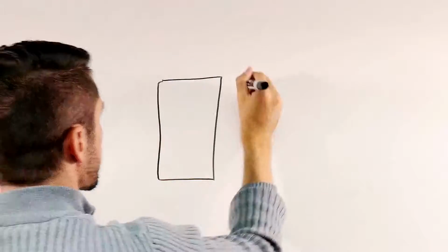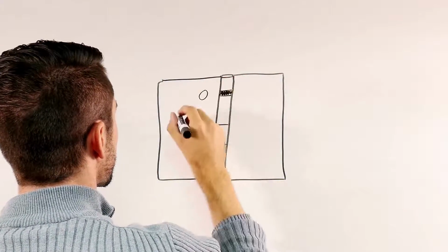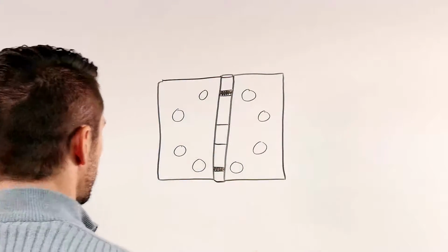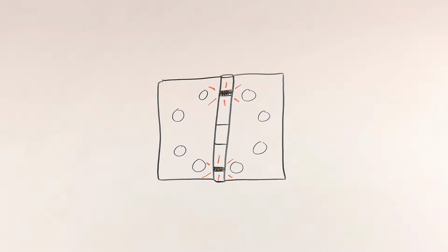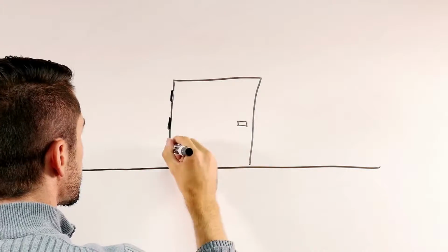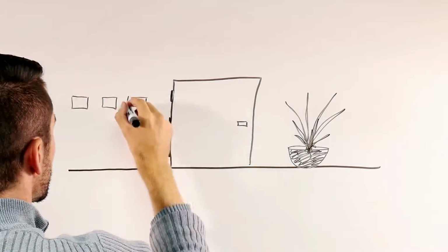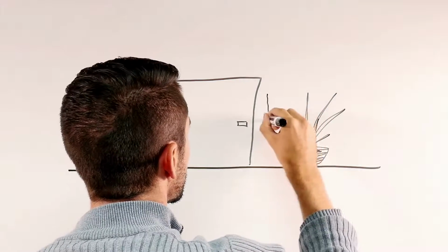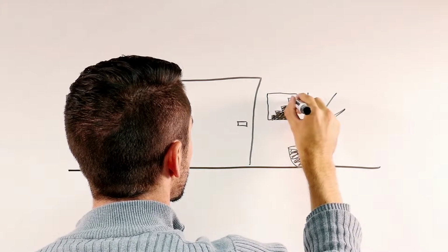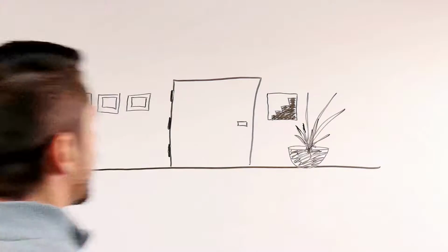Another key characteristic of conventional hinges is whether the hinge has anti-friction bearings, with ball bearings the most common type. In a 5-knuckle standard weight hinge, ball bearings are placed in 2 of the knuckles, either visible or concealed. Anti-friction bearing hinges are used on fire-rated openings, as well as any opening with door closers or automatic operators. If a hinge does not have any anti-friction bearings, it is referred to as a plain bearing hinge. Plain bearing hinges are routinely used in homes, but are rarely used in commercial facilities.